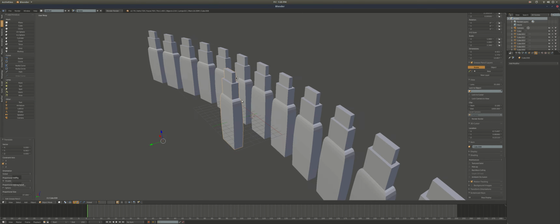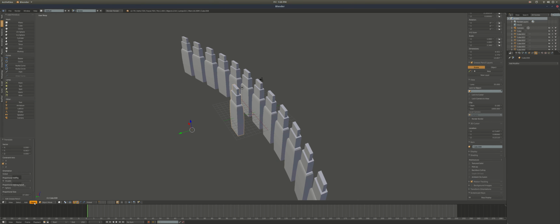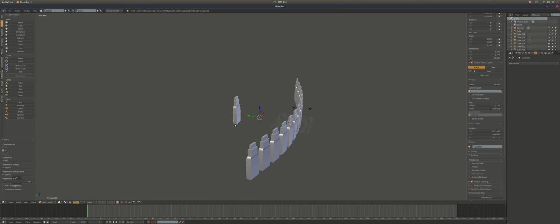And something that's handy is there's mirror modifiers, but there's also just straight mirror, and it's the interactive mirror. You just click the middle mouse button and drag it in the position you want to mirror it. Click the middle mouse button, drag it where you want to mirror it, hit enter, and it will mirror your object.